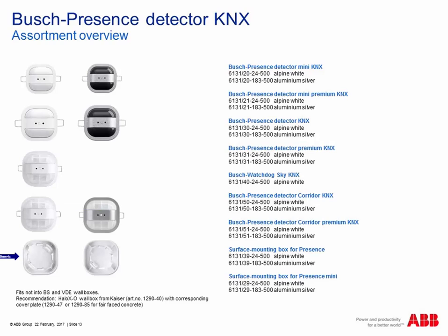Here are the surface mounting boxes, and if you want a flush mounted installation, here you can find our recommendation of typical boxes you can find in the market to use for flush mounted installation. One important hint: it does not fit into a VDE box if you are inside the VDE market. So here we also have an adapter ring, where you can also install it on a VDE box. So this is new.